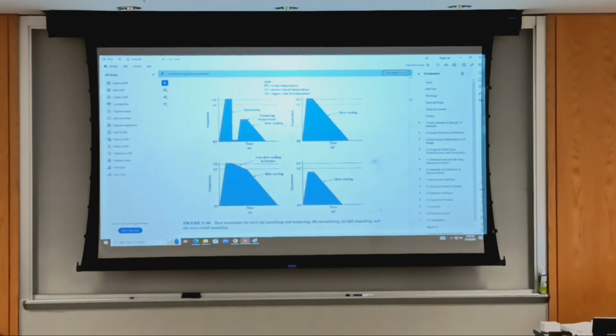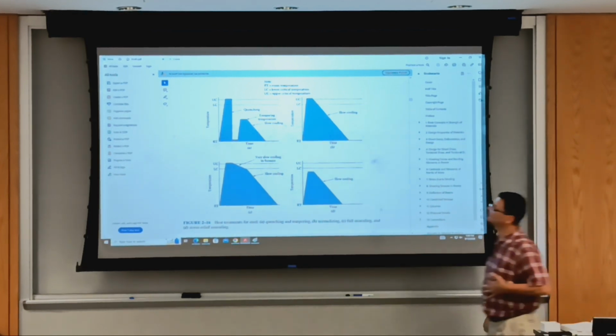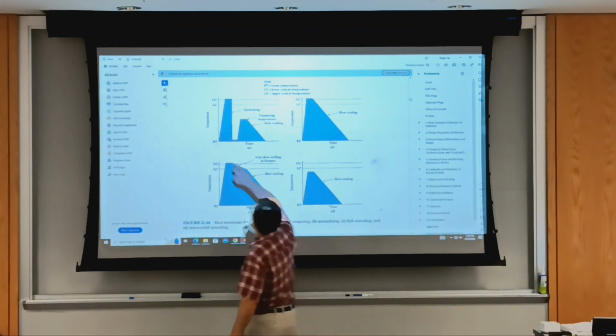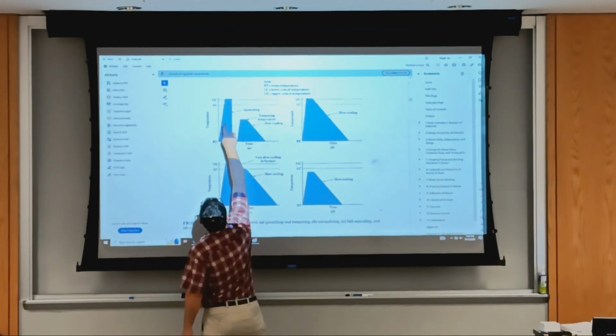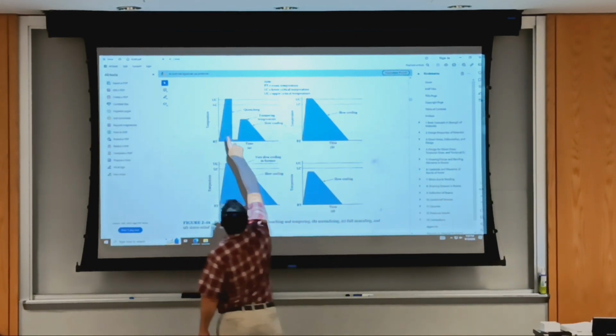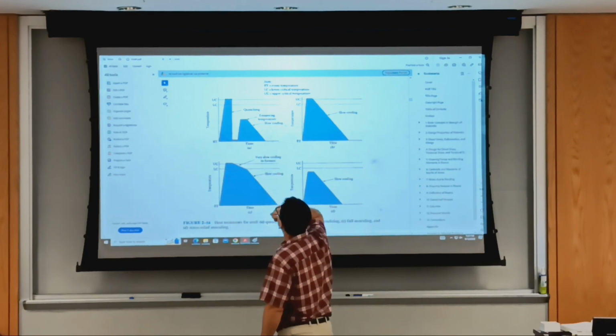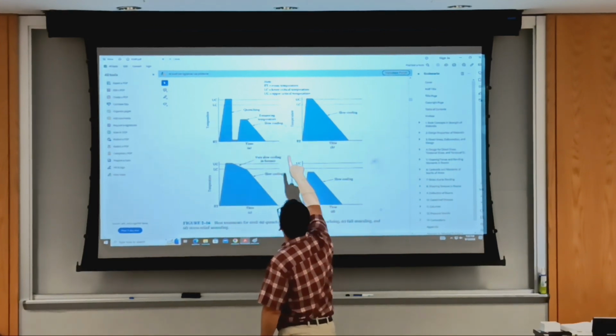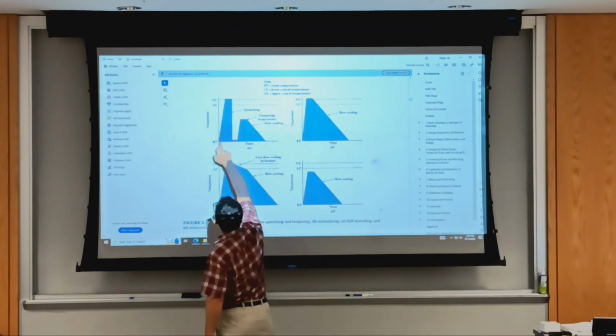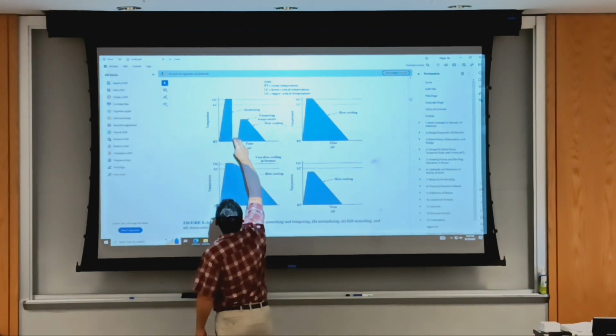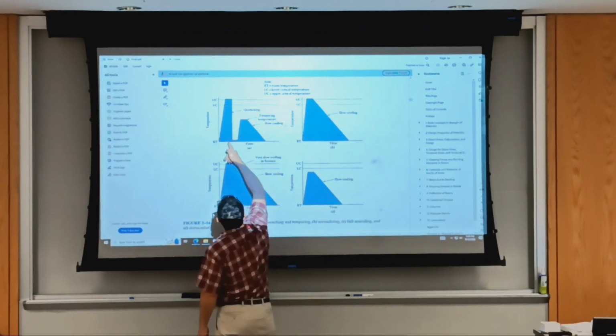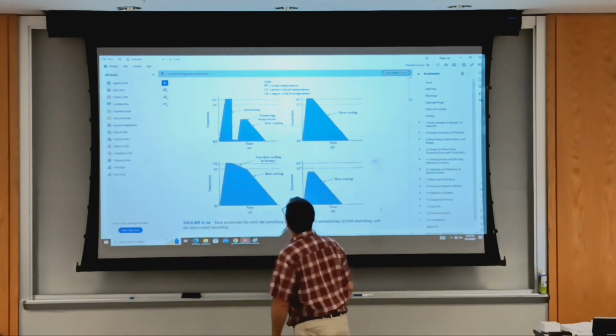This is a time-temperature diagram that is used for heat treatment. So this will be quench and tempering. So rapid cooling from above. This is the lower and upper critical temperature. This is room temperature. And of course, this can happen slower or steeper depending on the quenching medium. And this is the tempering.